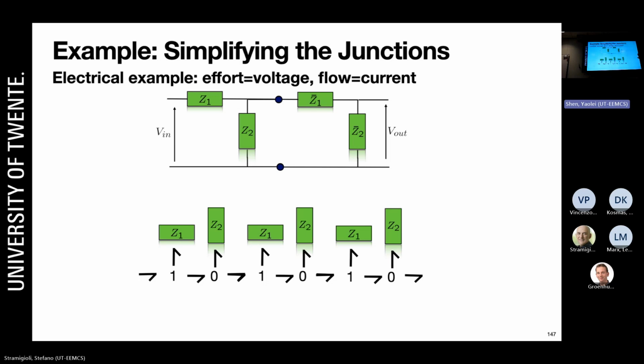Kirchhoff's law is still true in this definition. It is the fact that in your modeling, of course, a wire is never a perfect potential everywhere. Because if you go to certain frequencies, the wire does not behave as such, and you need to model certain things which are effects that at a certain frequency play a role. So you need to change your model.